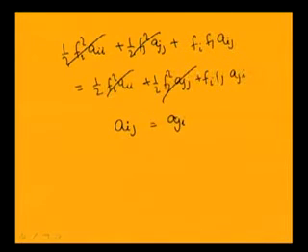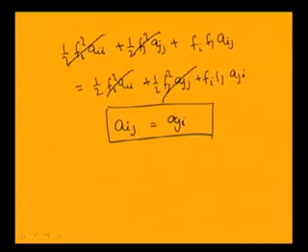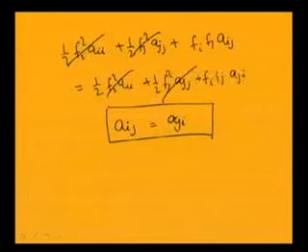So, this is the reciprocity theorem, and for a linear system you can have flexibility influence coefficient Aij equal to flexibility influence coefficient Aji, that is the displacement at i due to a unit force at j equal to the displacement at j due to a unit force at i. So, this is the reciprocity theorem.